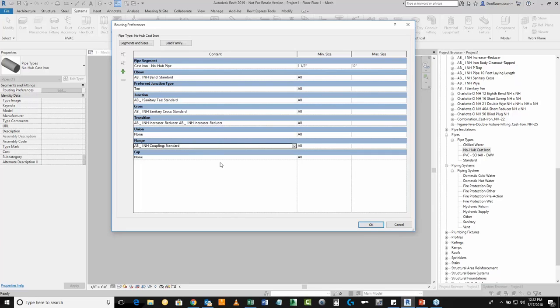And I got a question here about optimizing pipe lengths. There is no native tool inside of Revit outside of the fabrication tools for Revit that allows you to optimize actual Revit pipe lengths. I can do it with fab content in the Revit environment. There isn't a native tool to be able to do that with Revit pipe types like we're setting up right now.